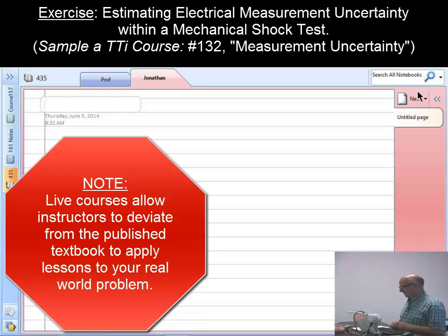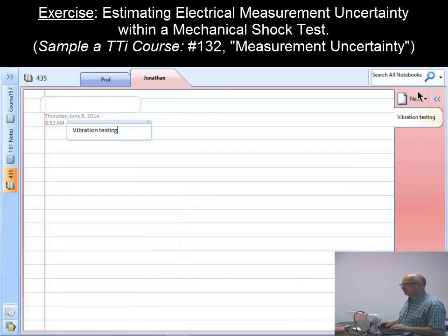I work in a test lab where we do a lot of dynamics and vibration testing. I guess similar for SwiftPack, we do a lot of D5 FBM testing where a lot of the electronic packages will get subjected to usually a sine. When I talk about vibration, it usually consists of a sine, shock, and a random vibration test. Is that swept sine or fixed frequency sine? Usually a swept sine, yeah.